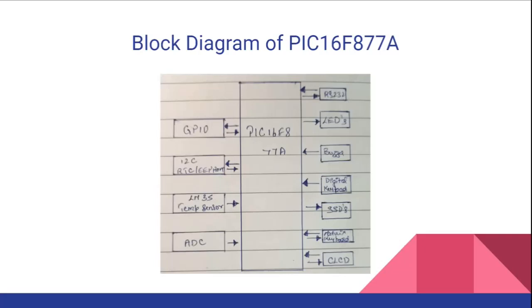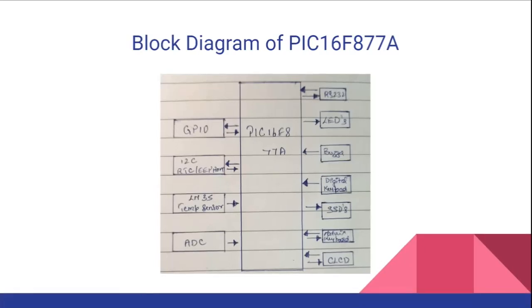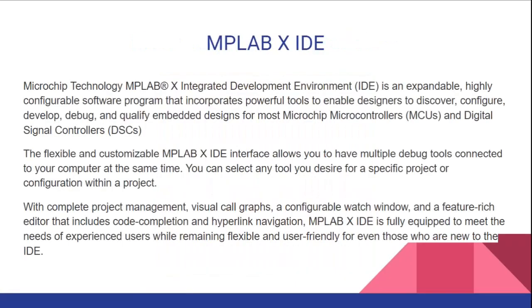It supports several devices that can be connected to the boards for simulation, for example LEDs and push buttons for outputs and inputs, and some more complex ones like Ethernet shield W5500 for internet connection, or the color graphic display ILI9340 with touchscreen.